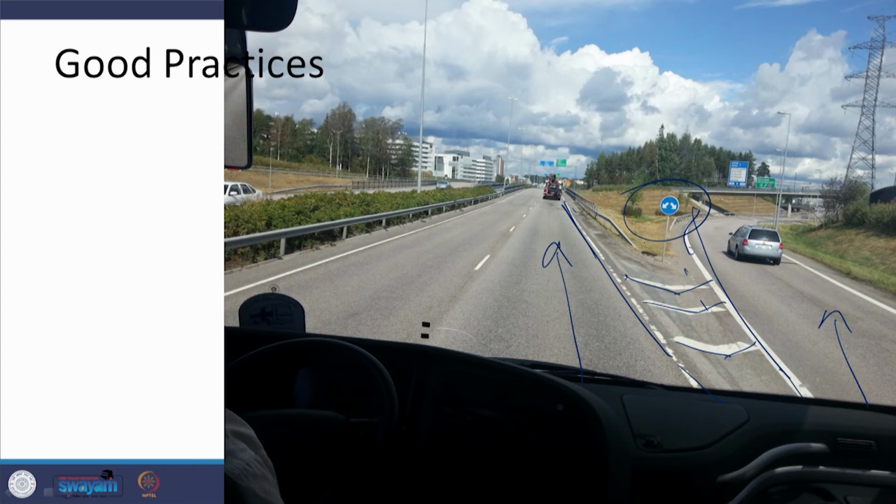At the same time, there is a crash barrier, and the crash barrier has been designed rightly at its culmination where it ends, and it goes into the ground like this. So that if any vehicle which is coming say from this side hits here, there is a possibility that it is not going to create a big problem to the passengers or the drivers in this vehicle, but if this had been a straight profile, then that would be more dangerous.